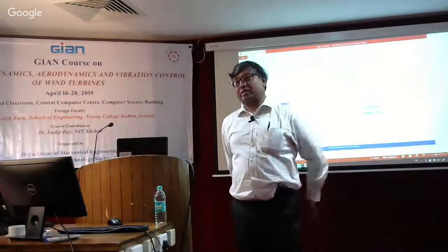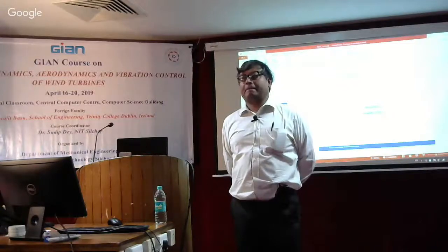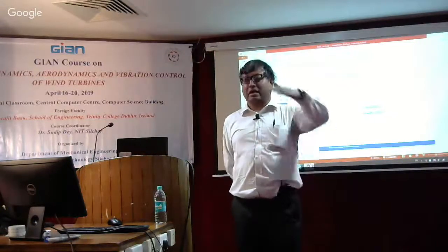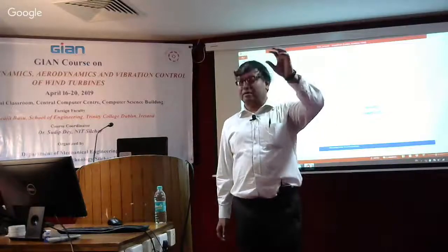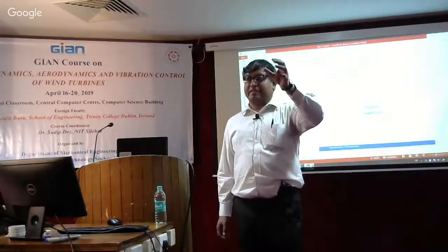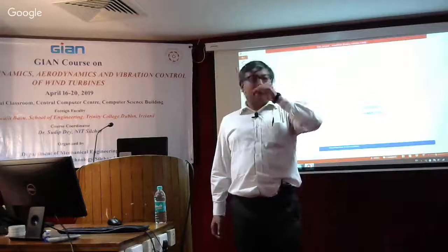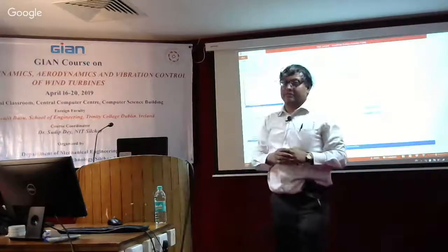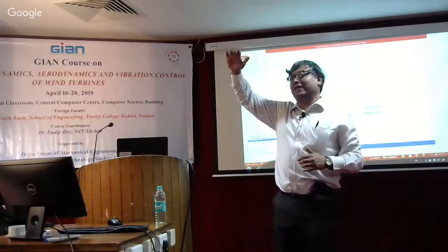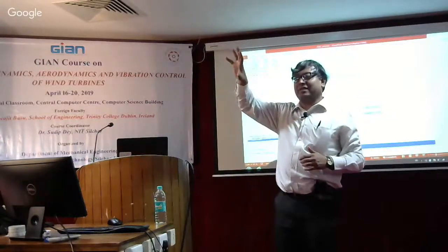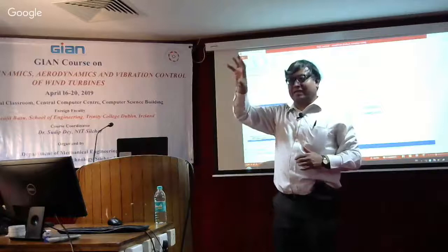That is your reference. So what is normally done is you put an anemometer. From the anemometer data, you have the velocity, say at 20 meter height. Then you use that to see what it would be at a height of 80 meter, because your hub is at 80 meter. So most of the power will be generated at 80 meter height.